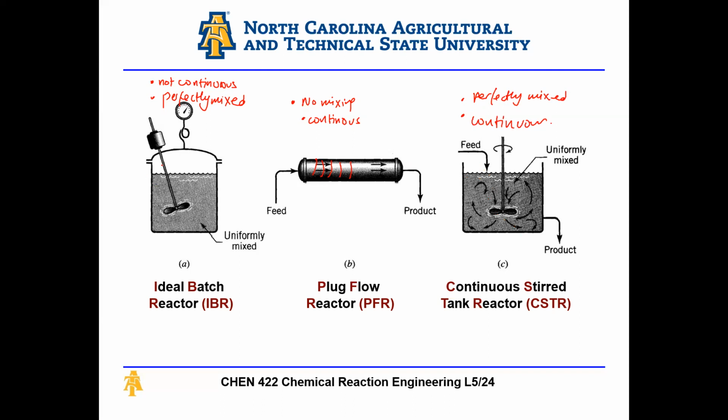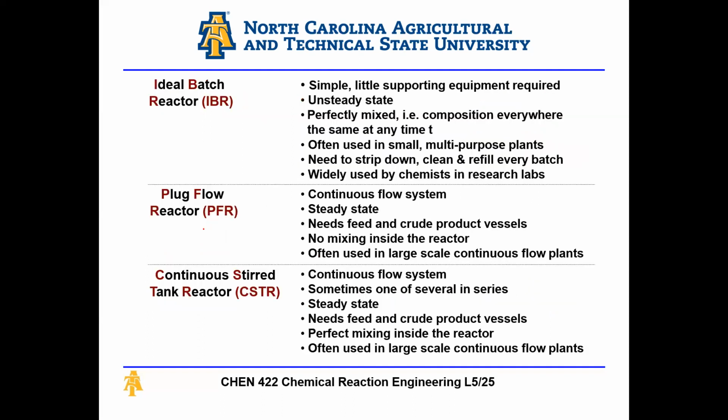this one I don't have flow going in and coming out. I charge it at t equals 0, and then at t equals t end, I just take the products, for a batch reactor, okay? So understand the three types of reactors, and understand the differences between them. This is really the core of this course, so it's very important that you know this. This is the slide with the differences, or the properties. So read it, and make sure you know what these are.